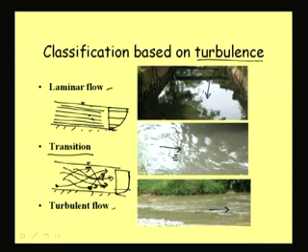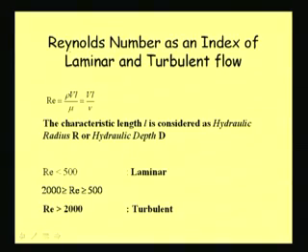Well, then as I am telling, probably you might be thinking, okay, what is transition flow? Laminar is this, understood clearly. Turbulent is this one, when there is a mixing up of the flow. And then what is transition? That of course, to define very specifically, we must take help of some index, and that index generally used is Reynolds number. You know very well what is Reynolds number. So that Reynolds number we express as rho VL by mu.